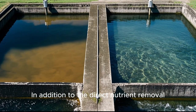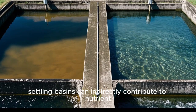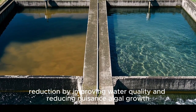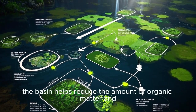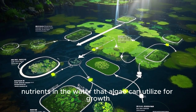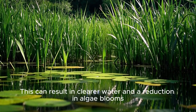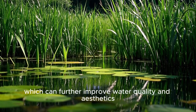In addition to the direct nutrient removal, settling basins can indirectly contribute to nutrient reduction by improving water quality and reducing nuisance algal growth. By removing solids, the basin helps reduce the amount of organic matter and nutrients in the water that algae can utilize for growth. This can result in clearer water and a reduction in algae blooms, which can further improve water quality and aesthetics.